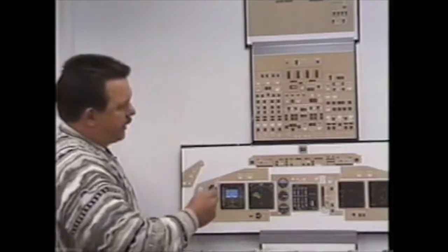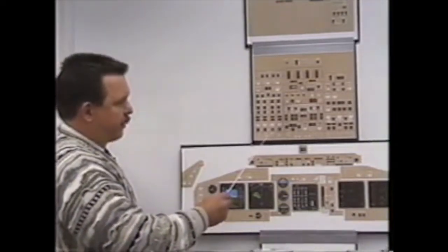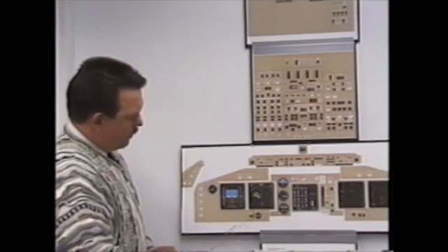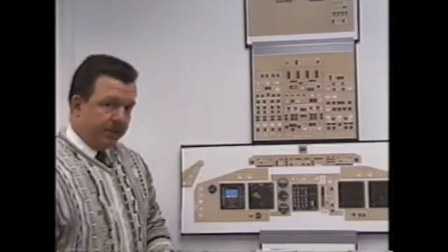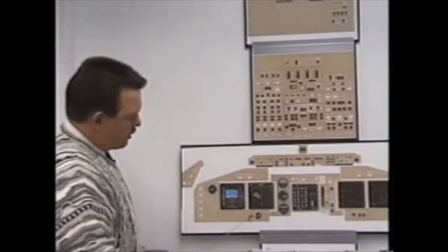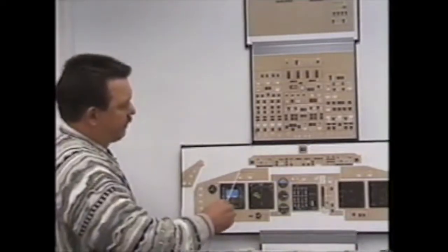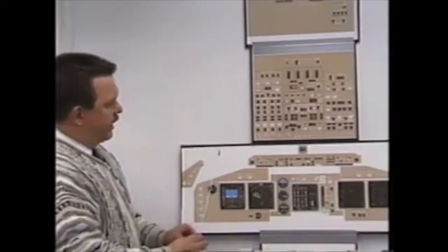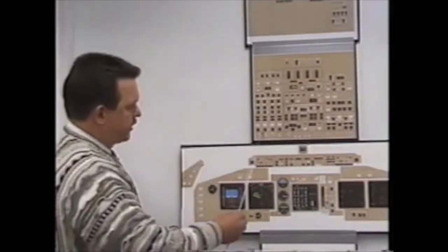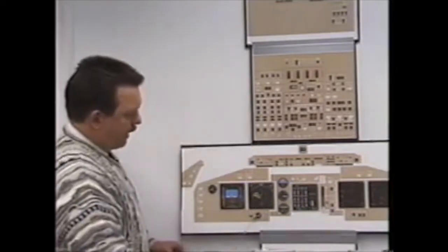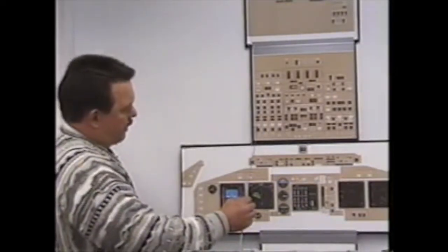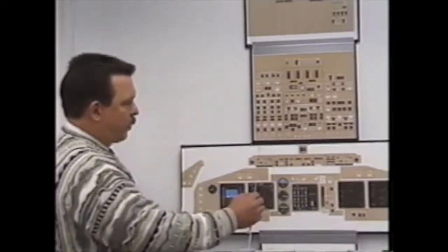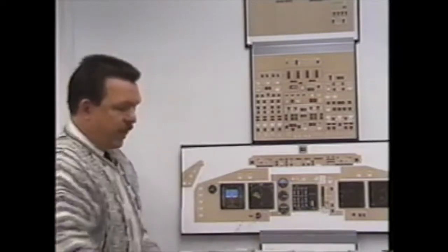I then reach up and pressurize hydraulic system number 4. System 4 is pressurized. That will bring the precharge up to system pressure, approximately 3,000 psi. The brake source light is out, indicating the brakes have gone from 1 over to 4. So what we've done here is I've gone in reverse order of priority. System 2 started it out, could not bring up the gauge. Pressurized 1, 1 took it from 2, again cannot bring up the gauge. Pressurized 4, 4 takes it from 1 and brings the gauge up.